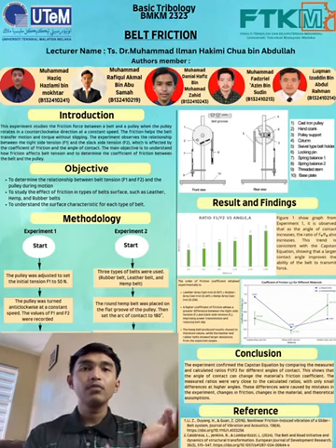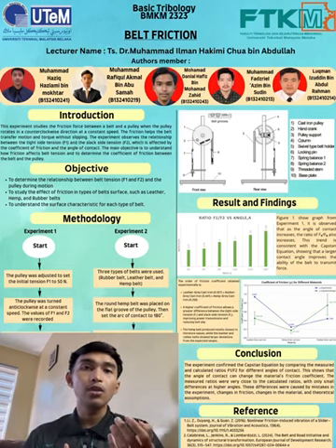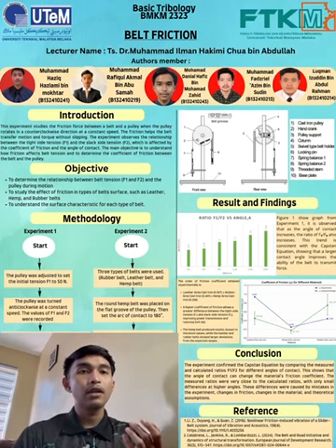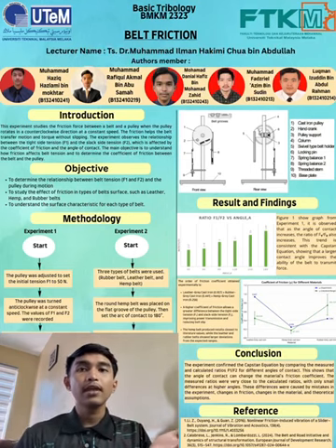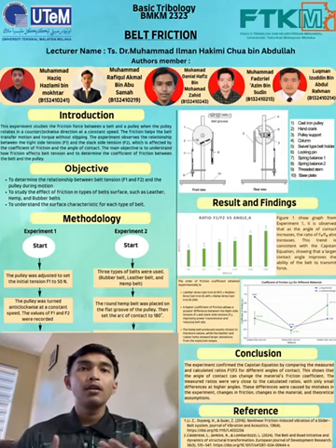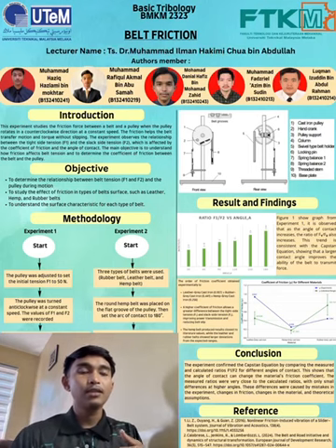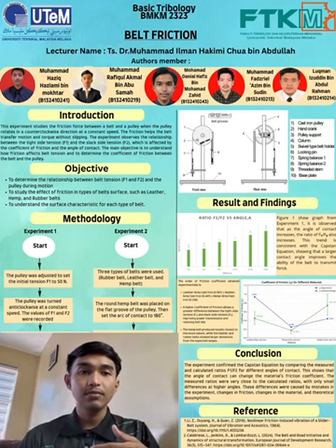The experiment confirmed the characteristic equation by comparing the measured and calculated ratio F1 over F2 for different angles of contact. This showed that the angle of contact can change the material friction coefficient. The measured ratios were very close to the calculated ratios, with only small differences at higher angles. These differences were caused by mistakes in the experiment, change in friction, change in the material, and theoretical assumptions.